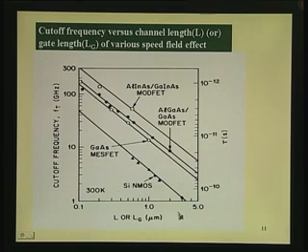So, you can see for 1 micron you can get about 2 to 3 gigahertz, and when you go down to 0.1 micron, which Intel is boasting of, 10, 20, 30 gigahertz is the cutoff frequency. That is how they are able to make this Pentium and all with frequencies which are in few gigahertz range, by reducing the channel length. So, in silicon you get this entire curve by varying the channel length, totally controlled by lithography.